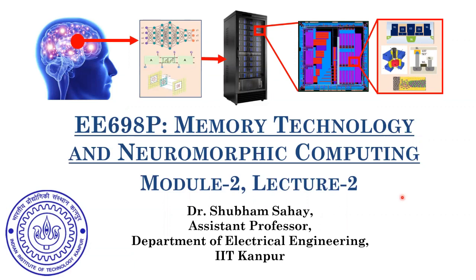In the last lecture, we saw how these memory cells are organized in memory arrays and why we need to design memory arrays with an aspect ratio of 1. We also saw how these large memory arrays are divided into several blocks, and how these blocks help not only in reducing the access time, but also in energy saving. Lastly, we saw how, by cleverly designing the peripheral circuitry, we can use memory cells which have higher density or use a low number of transistors without degrading the digital circuit conditions.